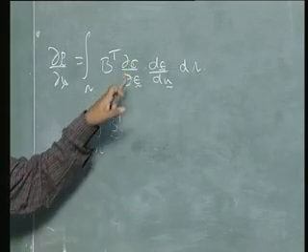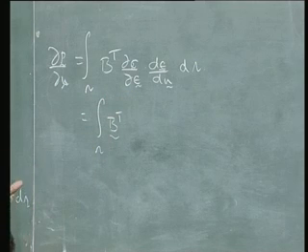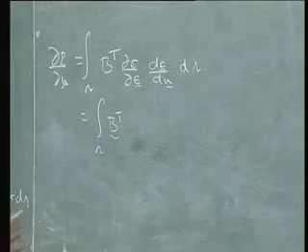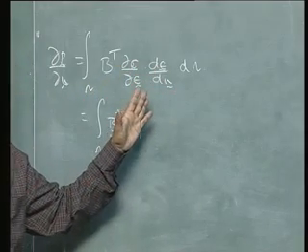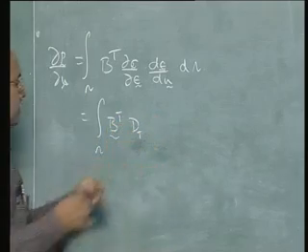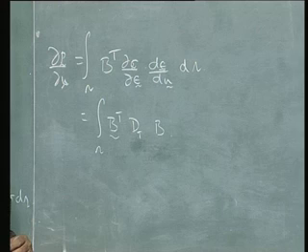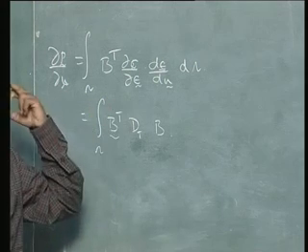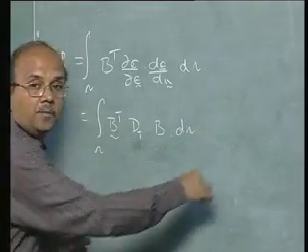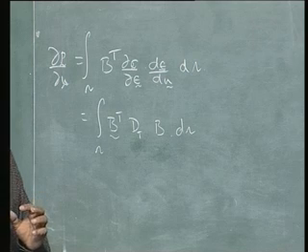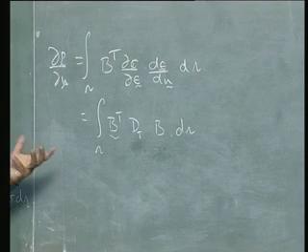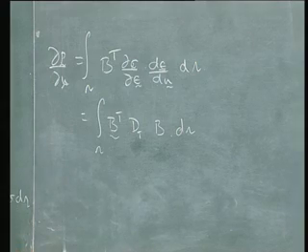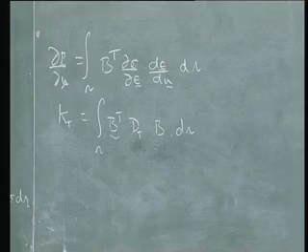So this becomes very simple. B transpose, of course, all of them are matrices. Let me call this d sigma by d epsilon as Et or Dt, however you call it. If you had called previously E, you call it E. Previously D, you call it D or Dt. I'm going to use them interchangeably because people are familiar with either E or D matrix. So Dt. Then d epsilon by du, what is this? Strain displacement matrix, so B. I've left out one of the things: you remember in the previous case, ∂P by ∂U is multiplied by delta U. Remember what we had for our Newton-Raphson scheme, P plus ∂P by ∂U into delta U. This is what we called the tangent stiffness matrix, KT.